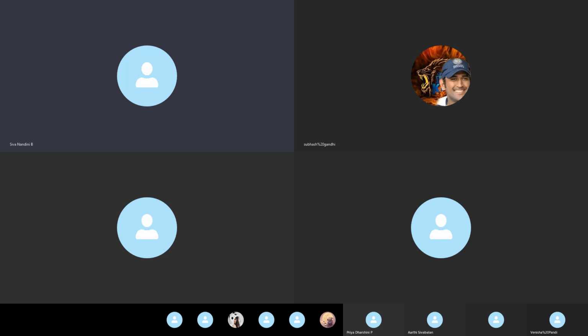Here, the dry film is attached to the plate to protect the hole, okay? Here, already the board is holed by means of drilling operation in the previous stages. After drilling only, this photo film is applied in the outer layer and it is imaged. So this dry film will be applied to the hole also, okay? And next, go to slide number 16.